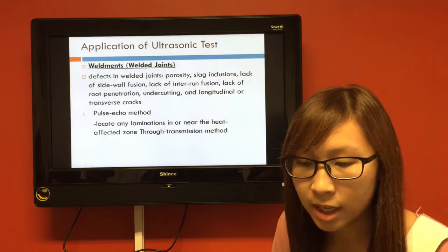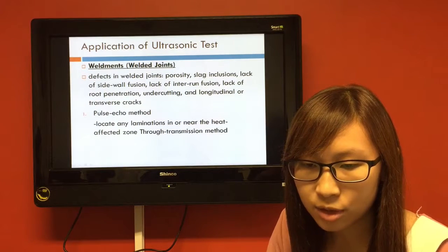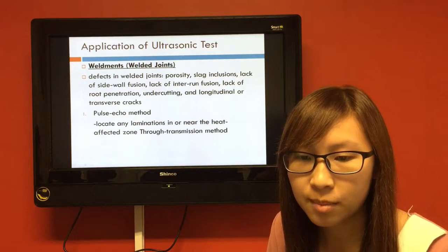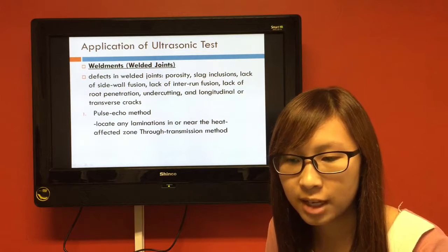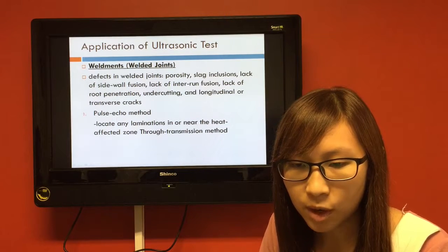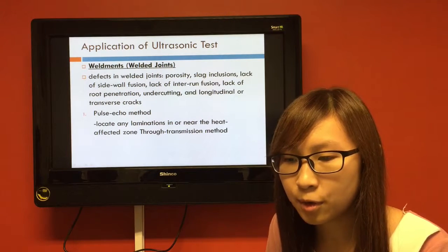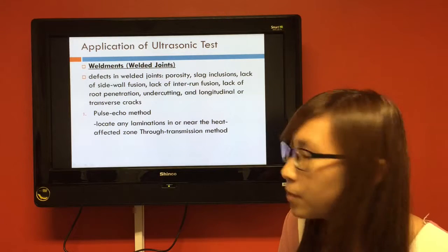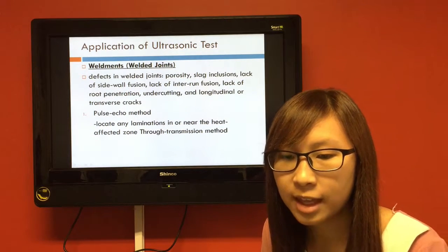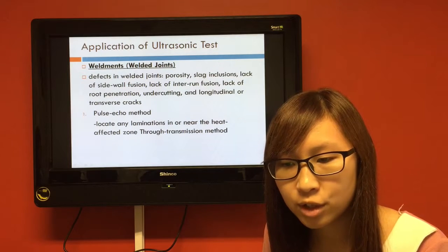Welds in aluminum can also be tested. Ultrasonic flaw detection has long been the preferred method for non-destructive testing in welding applications. Ultrasonic weld inspections are typically performed using a straight beam transducer in conjunction with an angle beam transducer and wedge.